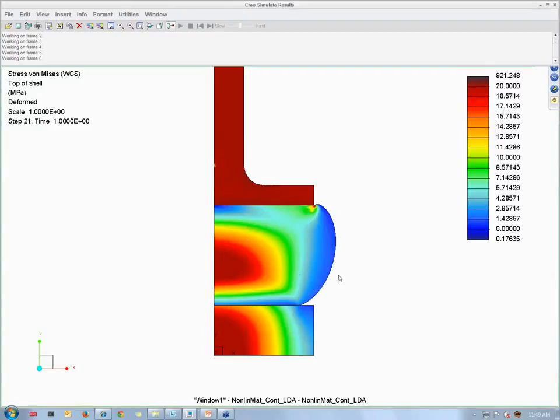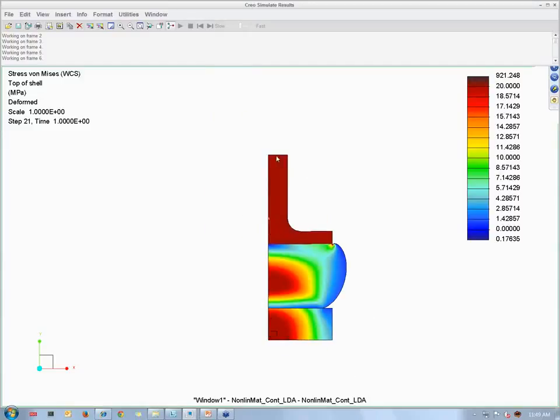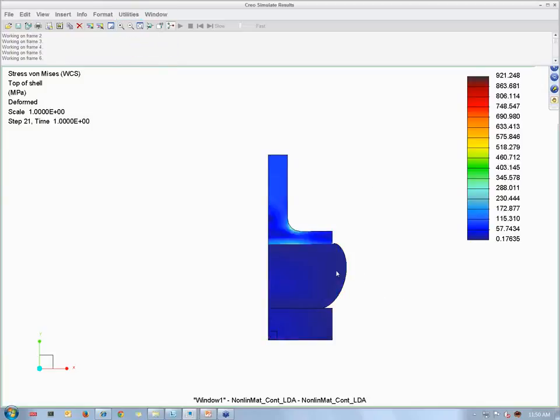What we are seeing now is the stress inside the rubber, and we can see the actual concentration of that in our object. We see the plunger at the top all in red because it's above the 20 megapascals. But again, we've only changed the range so I could see what the actual stress distribution is on the inside of the rubber. If we go back to the original legend, the stress inside the rubber is so small in comparison to what it is on the top.